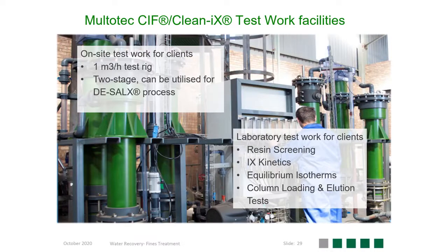We believe that the best way to approach these situations is to do test work. We've got the capabilities at our facilities to do laboratory scale test work for resin screening, IX kinetics, equilibrium isotherms, column loading and elution tests, as well as pilot testing. We've got a 1 cube an hour test rig, which is an exact replica of the desal X system.